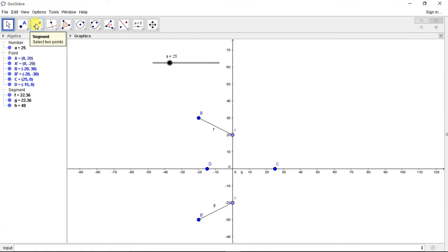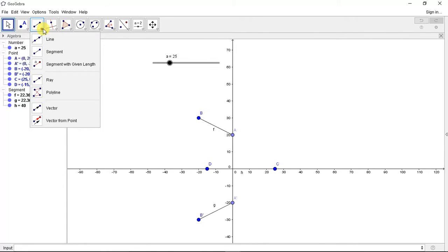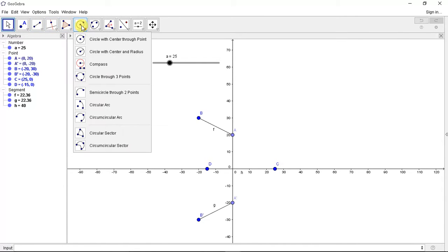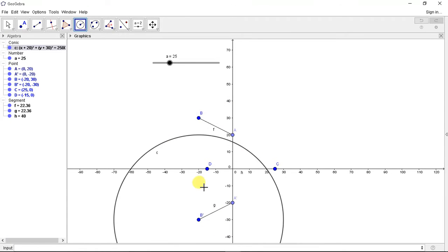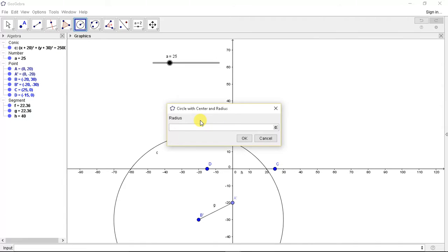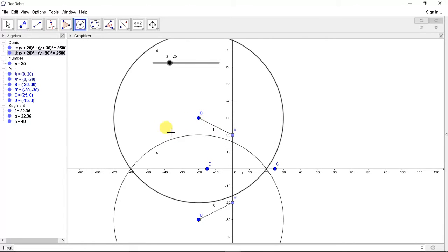Okay, now we know the length of the gripper, so we will define a circle with that radius. We know the length of the gripper to be 50, so we will make two circles of radius 50, and see it intersects at 60. So when we are at the extreme position, the closing condition should be this point D should come to 60.